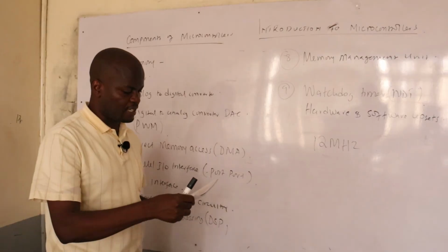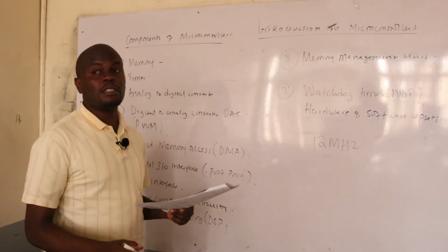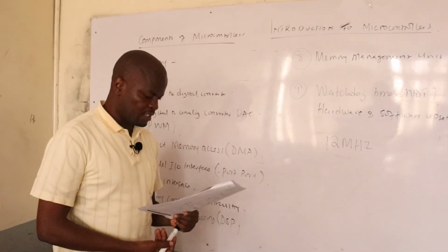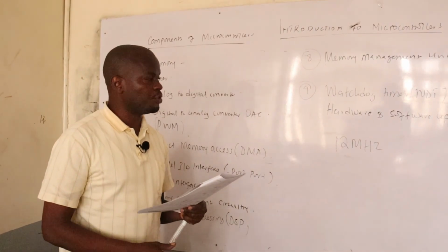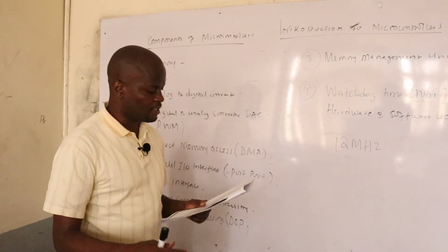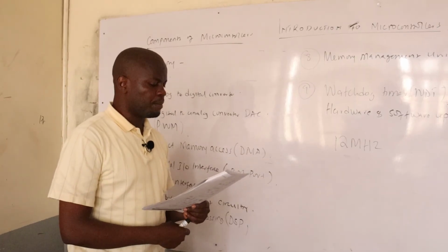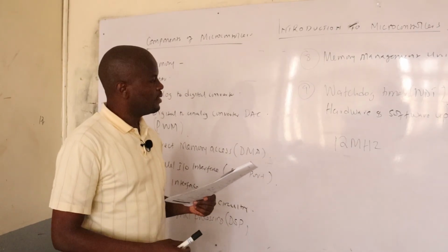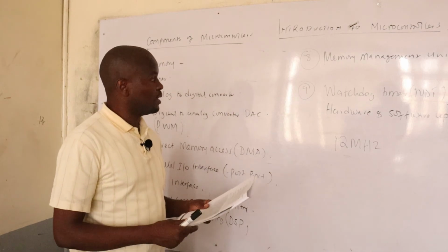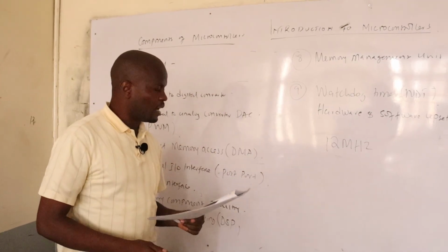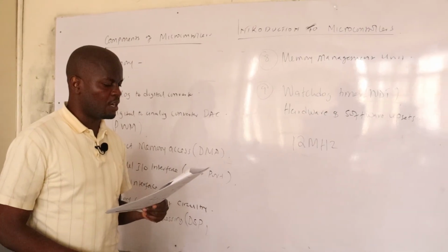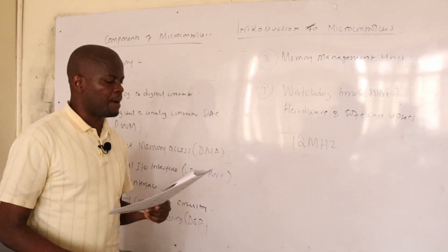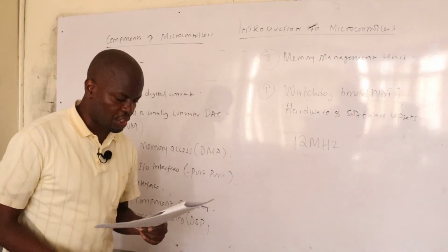We usually refer to that as a malfunction, especially if it takes longer than the time that is required, because each and every process usually has allocated time within which it can be processed. And if it takes longer, that will call for the WDT, and the WDT will reset and also stop in order to avoid a malfunction in operation.